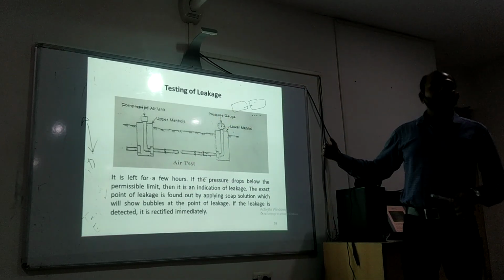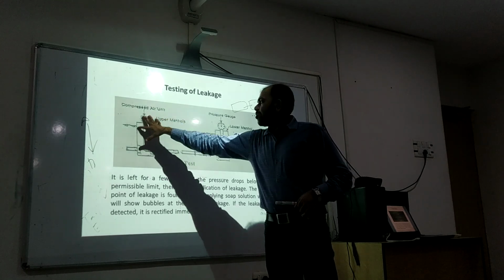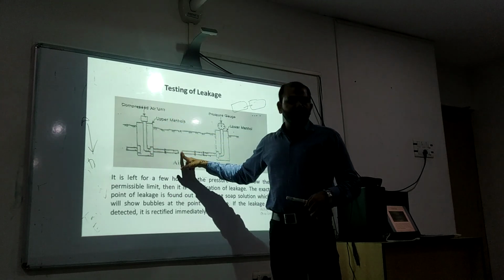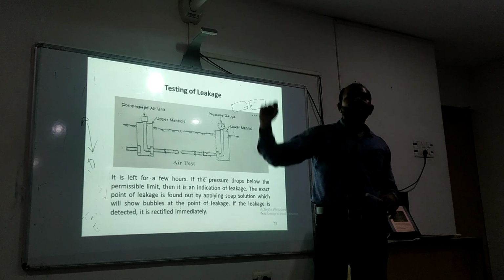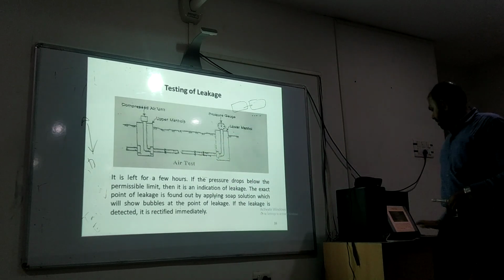And in the smoke test, I have told you, at one end fire is created with the end blocked, and smoke is pushed inside. If there is leakage anywhere, smoke will come out and indicate that there is a leakage that has to be repaired. ठीक है?